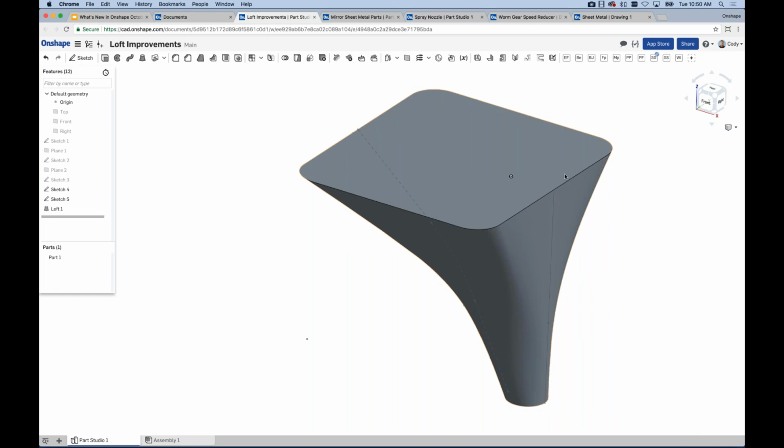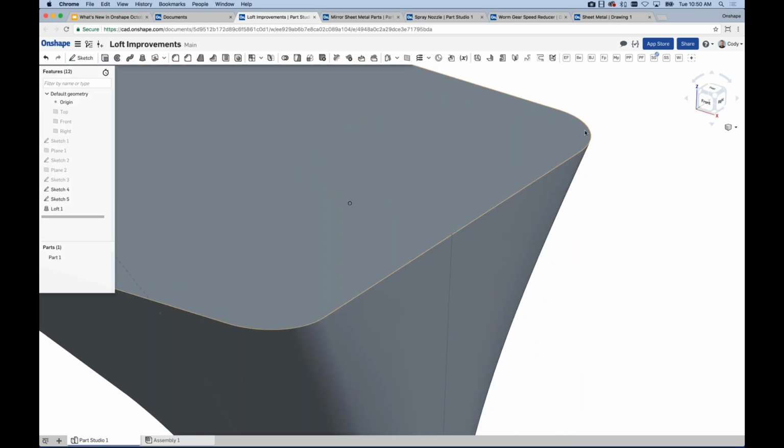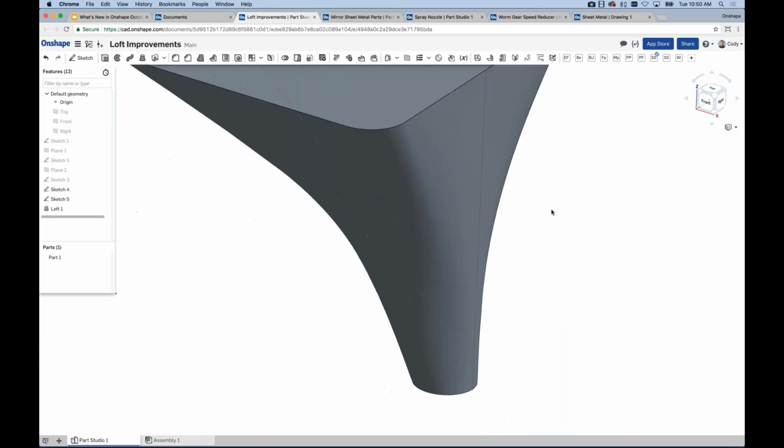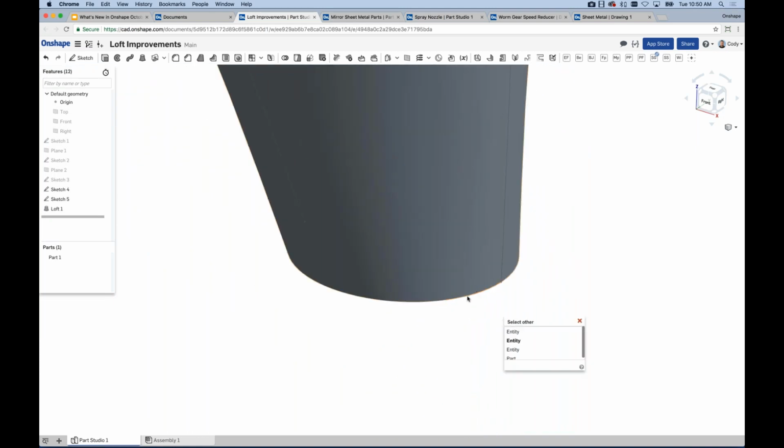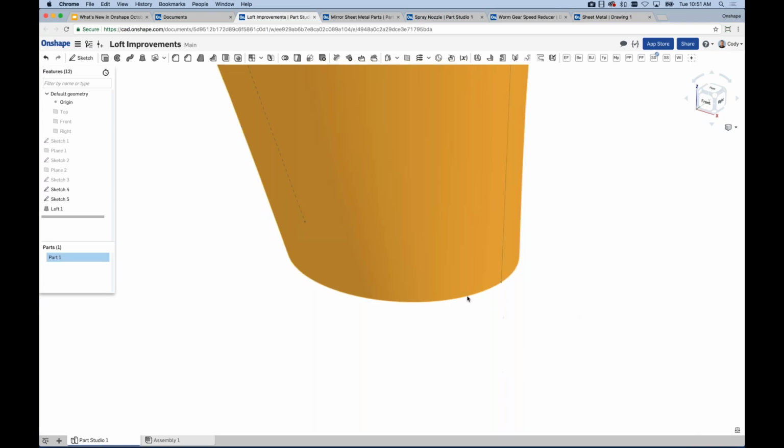Now, another question then is, well, if I mouse over this, I hit the grave accent at the top left. Forgive me if I'm mispronouncing that. But it's the key just below the escape key, the tilde symbol. If I select that and then I hit it again, it goes through the selections. It goes through the list. This means that I can go through the list of select other without touching the mouse, and I think that's the key thing. So if I mouse over an edge, say I mouse over this edge, I hit the keyboard shortcut, select other appears, I hit the keyboard shortcut again, it drops down in the list. And you can see I'm going through all of these, right? All I need to do is hit enter, and I've selected that select other selection.